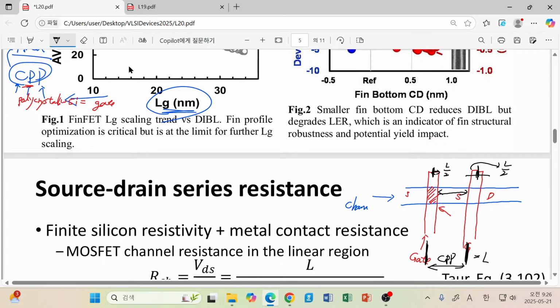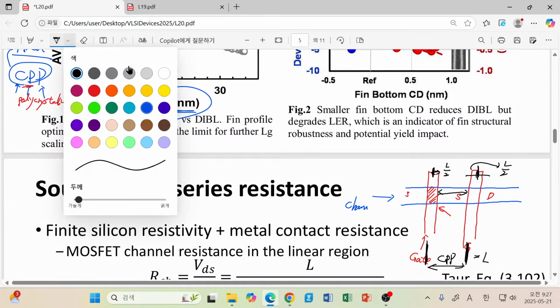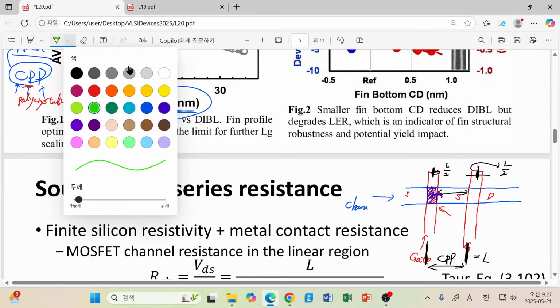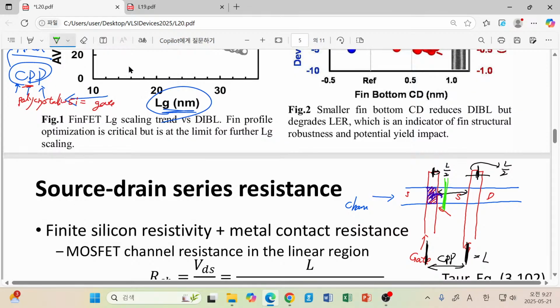But in reality, please be careful. If we make it just this way, please think about this one. If we introduce gate, which is metal covered, and if we have source and drain, although this is not contact, let's say that they are contact, then there is no separation between these two metal parts or two different contact parts. So although this is not contact, we usually want to introduce a certain separation between this gate and the actual source and drain.